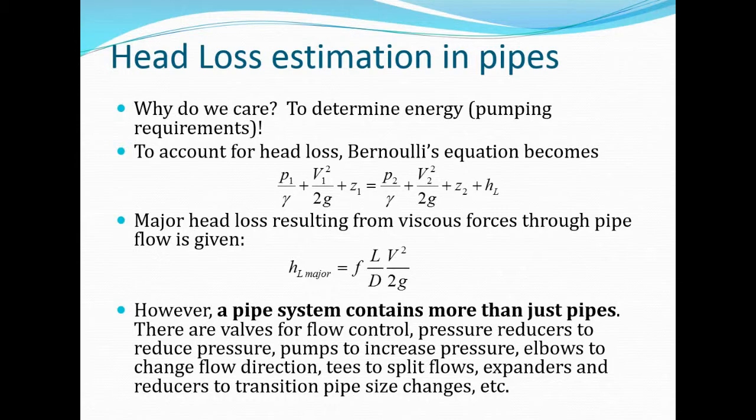So why do we care about head loss in pipes? Well, I think you already know that. We have to determine the energy in order to know how much pumping we're going to need to do. And we'll learn about pumping more in Chapter 12. So we have this head loss with energy in it. We've seen that before. And this head loss, we used to be sort of given, or we'd figure out what the head loss was from the problem. But now we're going to figure it out just explicitly from the velocity mainly and the pipe characteristics.